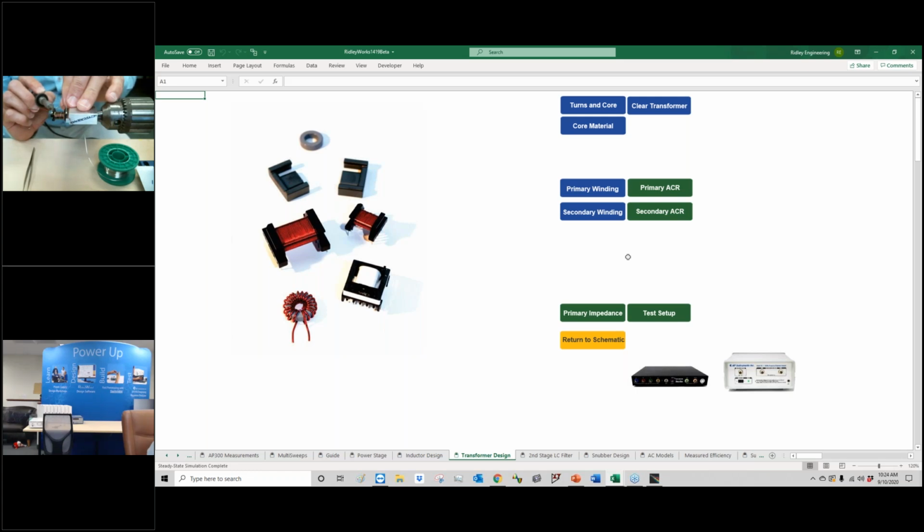Taking a little longer to burn through this time because we've got 2 strands to burn through. A little bit more conduction away from the soldering iron. See the smoke coming off. Looks good. And then we're going to solder the other secondary pin. Now you have to be very careful on these bobbins because the pins I'm soldering to are the same ones that plug into the board. So you want to try and keep them clean. So you keep all the solder close to the bobbin.